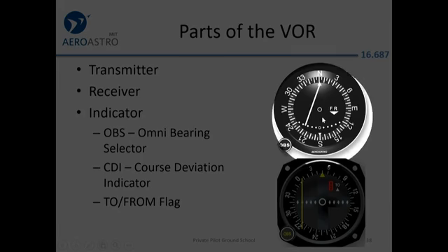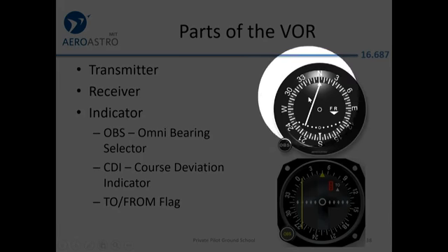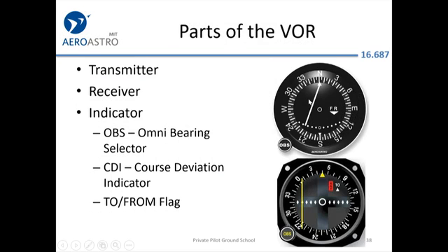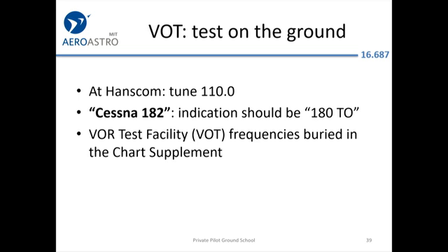And if we were to fly, this is not related to the actual heading of the aircraft. But if we were to fly basically north, we'd be going away from the VOR. OK, we're going to get into this more. The HSI down there offers you the same information, but superimposed on the aircraft's actual heading, which makes life a lot easier. OK, how do you test your VOR and know that it's actually going to work?